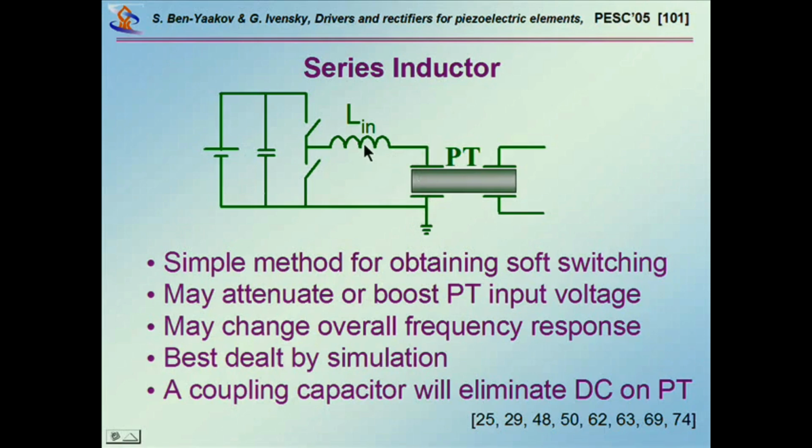You don't want to work at a very different frequency, too low or too high, related to this resonance, because obviously if you go to a very high frequency as compared to the resonant frequency, you'll have attenuation here, because this is a low-pass filter.